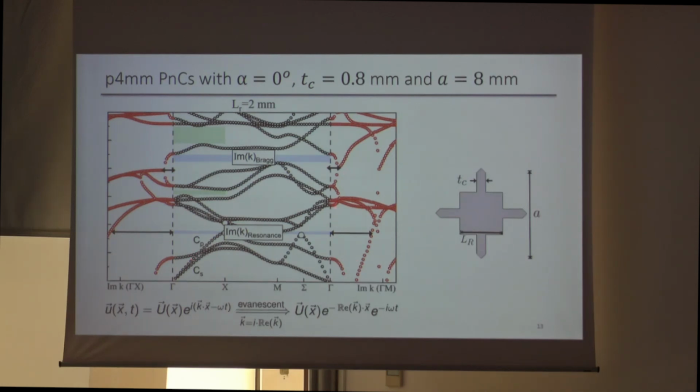But if we look at the real spectra for imaginary wave numbers in this direction, when we have the band gap, we will have this large distance for imaginary k until we get the real eigenvalue. And if we plug the imaginary wave number into the plane wave expression, we see that the value of this k tells us how quickly and how strongly the wave will attenuate.